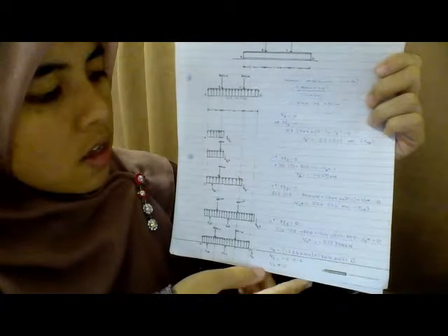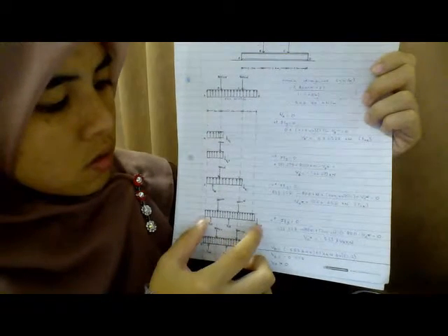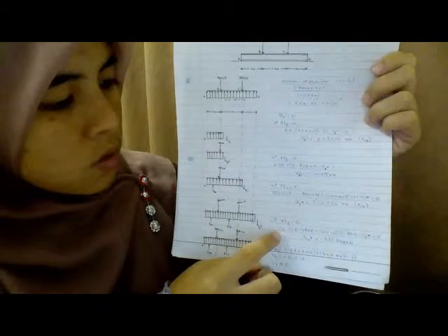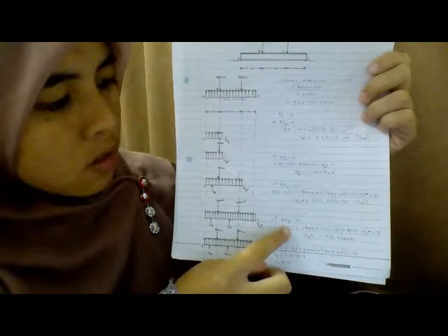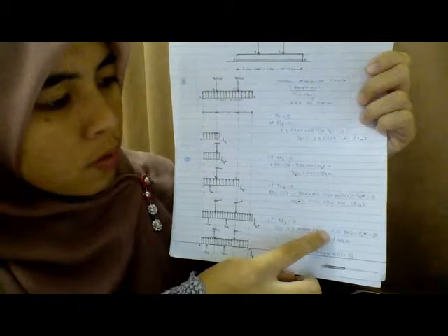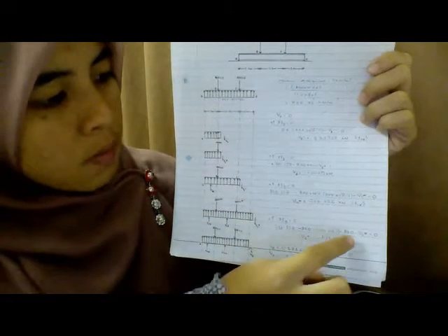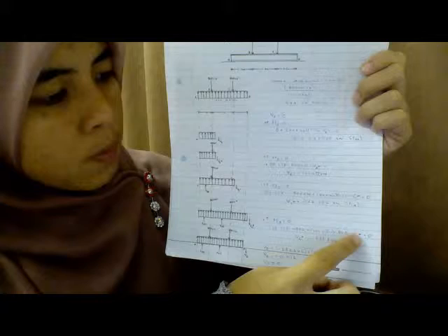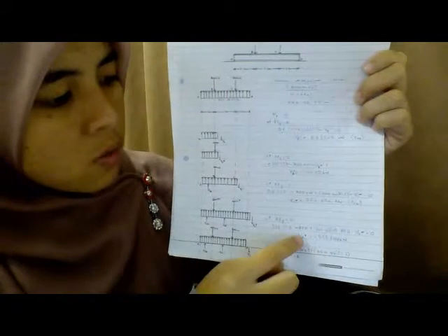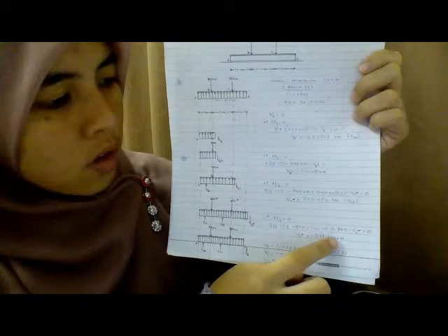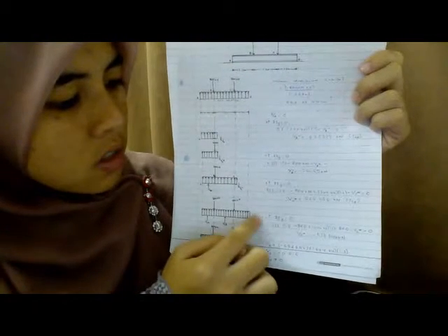And then the next is also the same. We use the summation of Fy equal to 0. So 533.328 minus 800 plus 444.44 times 1.2, it is from here, minus 800 kilonewton is here, minus Vc plus equal to 0. So the value of Vc plus is negative 533.344 kilonewton. So the value is Vc plus here.